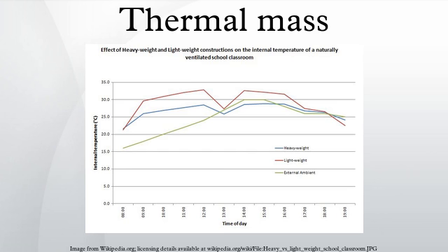Materials commonly used for thermal mass. Water. Water has the highest volumetric heat capacity of all commonly used materials. Typically, it is placed in large containers, acrylic tubes for example, in an area with direct sunlight. It may also be used to saturate other types of material such as soil to increase heat capacity. Concrete, clay bricks and other forms of masonry.